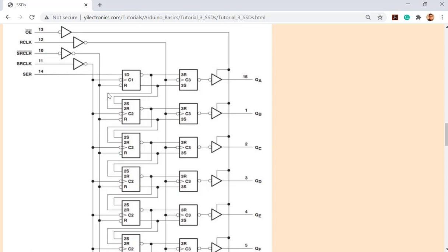Because this is the same wire, it's going to wait here for the next SR clock's rising edge. Whenever the next SR rising edge arrives, it will be transferred to here, and then wait here. And then another rising edge, boom, boom, boom. Is that data being shifted? Yes, it is. So think about, you have a series of data.